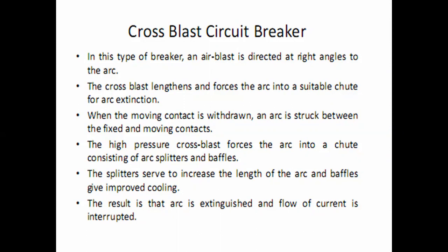So when the moving contacts are pulled apart from the fixed contact, an arc is struck between them, so you have to extinguish the arc in the minimum possible shortest time. What will happen when the arc is generated between the moving contact and the fixed contact? A blast of air is provided with the help of the air valve that is placed in the arc chamber. But the blast is provided in a perpendicular direction, at a 90-degree angle to the direction of the arc.